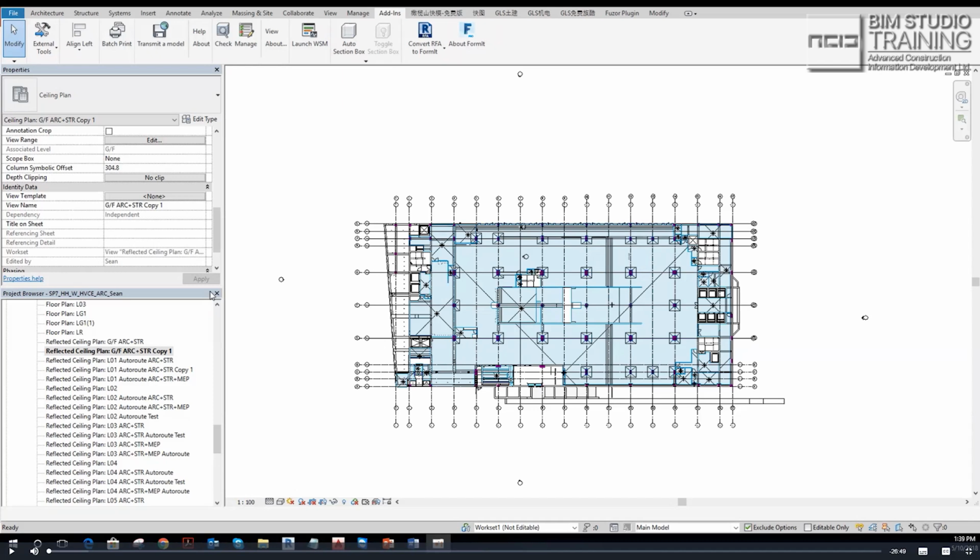So let's say the duct. If you want to run a duct from here to here, the first thing I would like to run is the most chunky. So what are the obstacles? One is A to B. The obstacle is that I must be above the ceiling. The architect defines the ceiling. If I don't have an opening at the bottom of the beam, the size of the beam is my limitation. I need to fit in and find a place between the ceiling and the bottom of the beam. So I first run my duct. My obstacles are the ceiling and the beam.